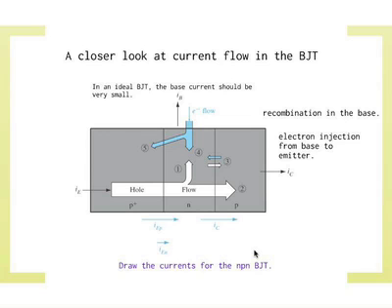Yes? So IC is always less than IE, right? Yes, that's correct. When you're trying to do amplification, do you give the signal to the IC end? No, to the IB. The collector is always the output. That doesn't really change. The control can change. The control can be the emitter, as I've shown here. Then in that case, you're absolutely right.